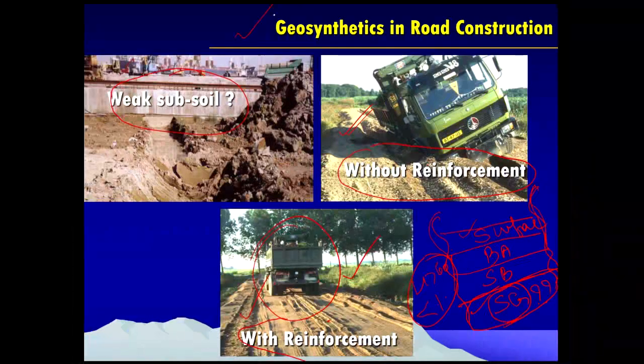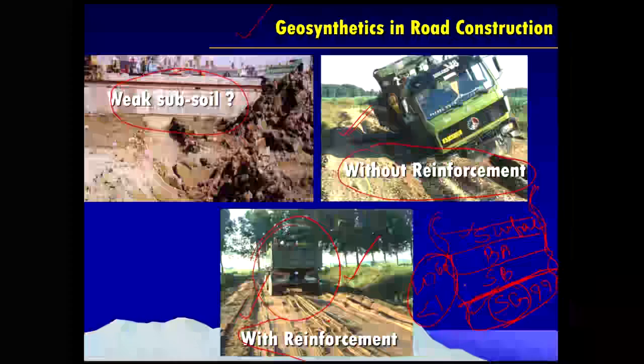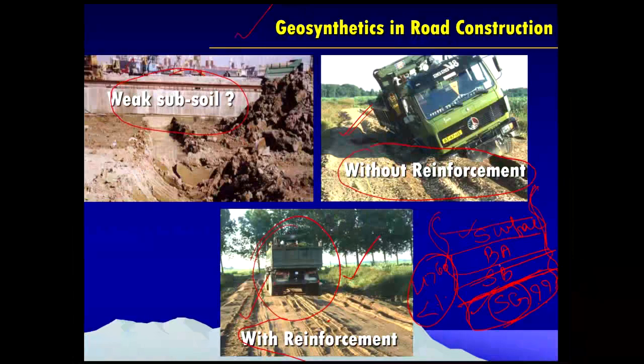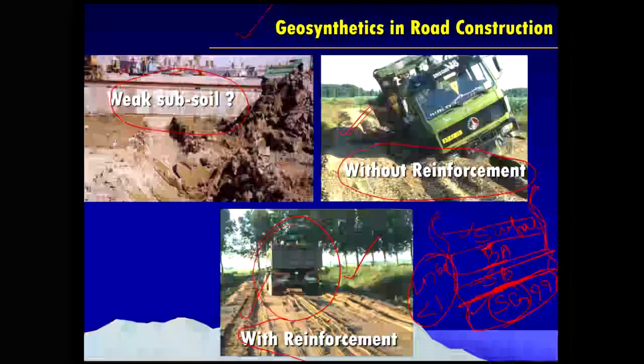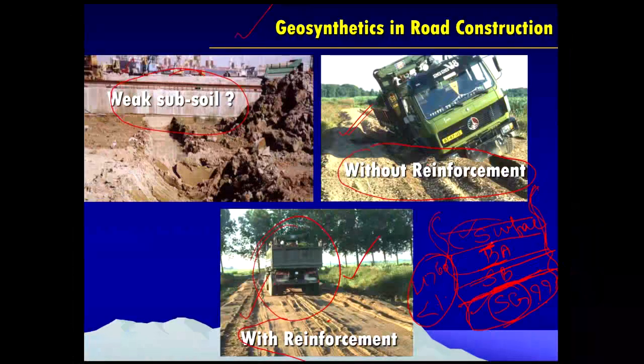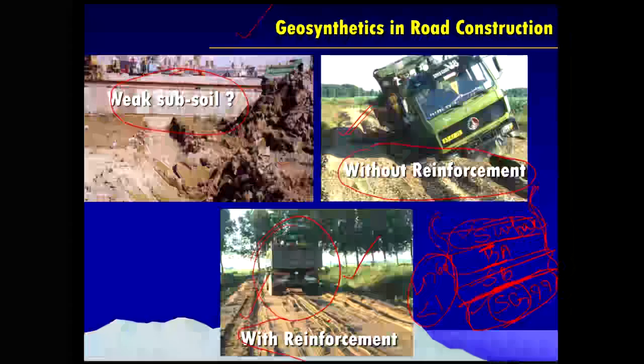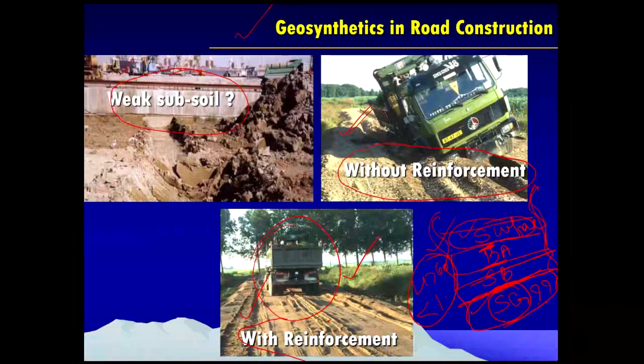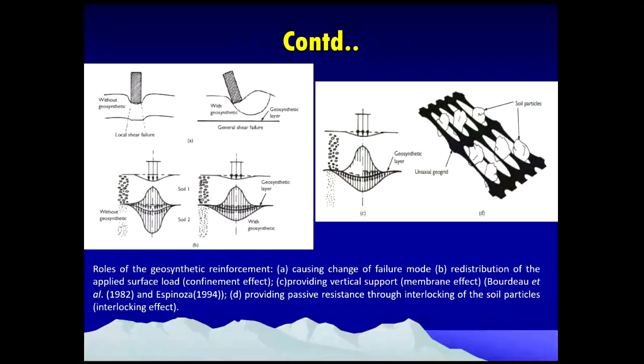Not only for subgrade improvement, it can also act as an interlayer within the layers. We can place the interface between the base, subbase and subgrade, as well as within the asphalt layer overlay thickness, with these materials properly treated. So we have different applications of geosynthetics. This is what we witness with reinforcement and without reinforcement.